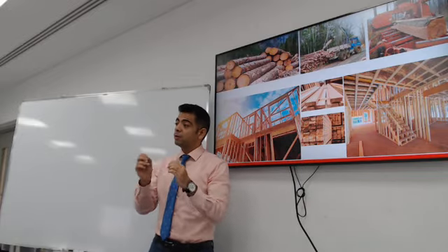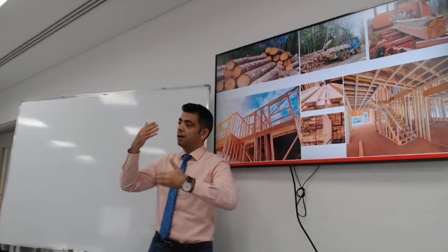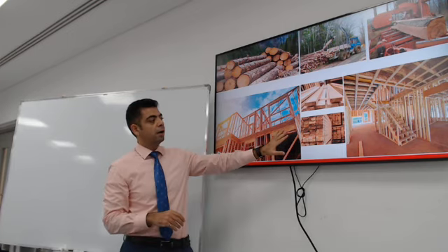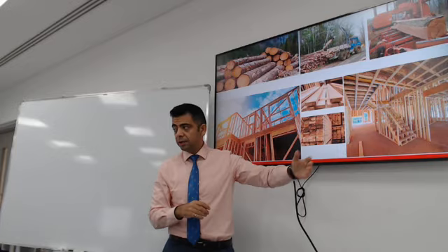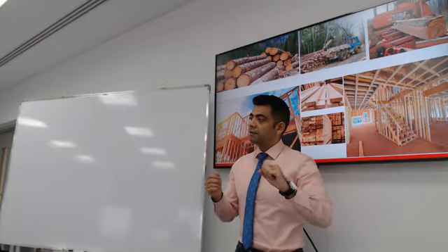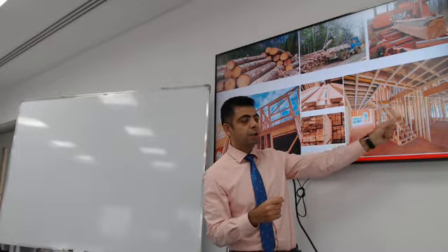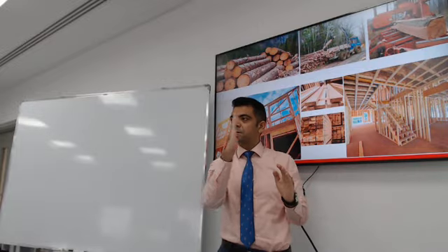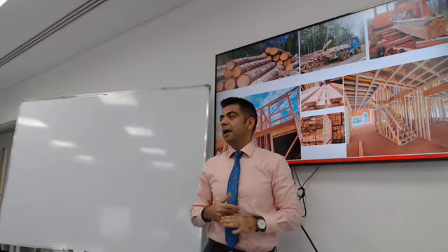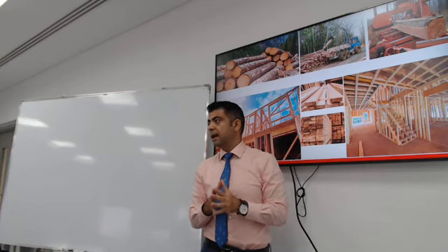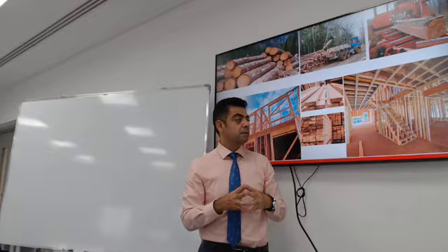You can create different products with wood. You can create sheets, planks, logs and different types of individual elements, and you can definitely use it in construction. It's lighter than steel, so individuals can actually carry these studs. These vertical elements are called studs, and then you put sheets on them and you can form walls. Then you can paint it, finish it, and this is very typical for single family residential buildings. It's relatively fast, it's affordable if the wood is available, and it depends on which part of the world you're practicing engineering.